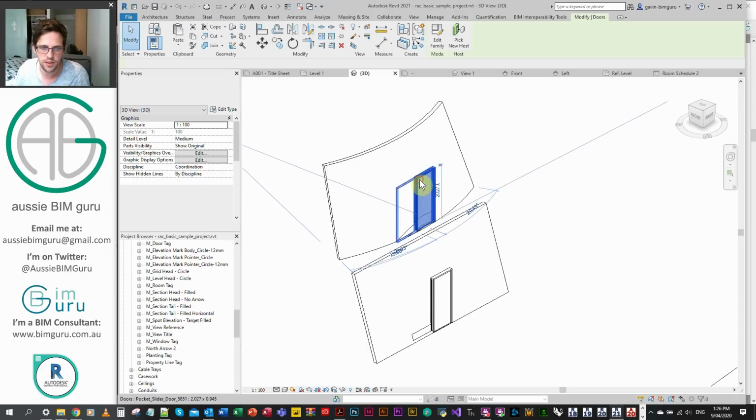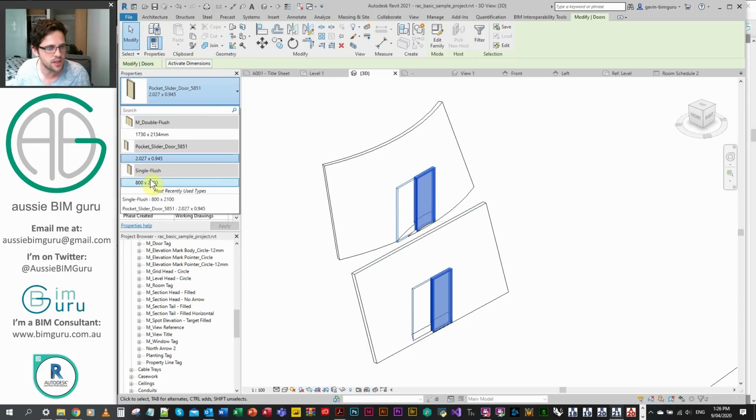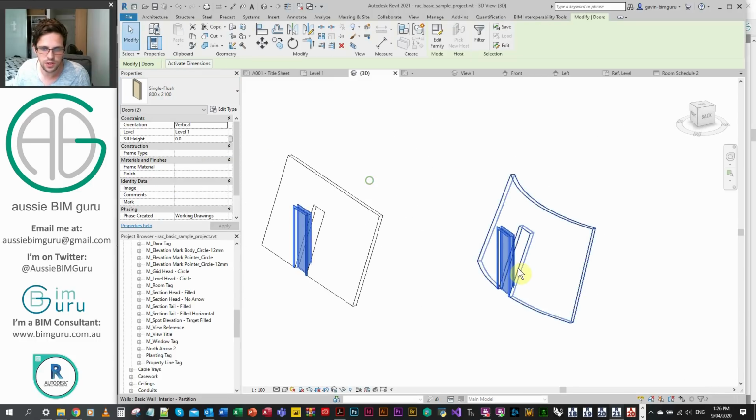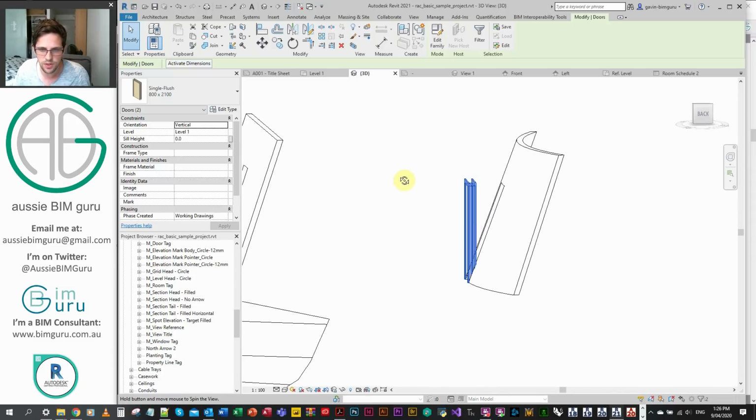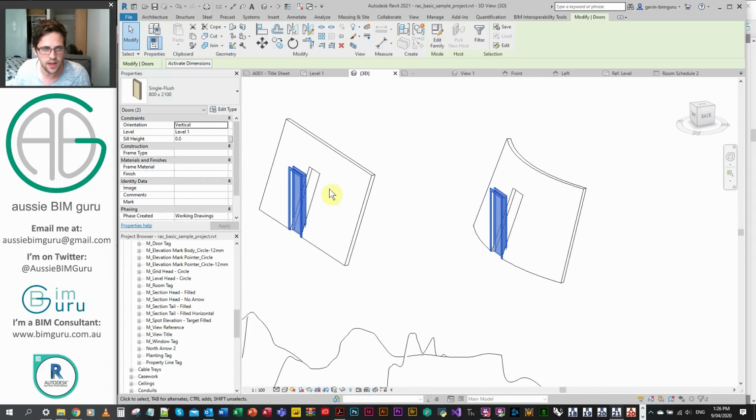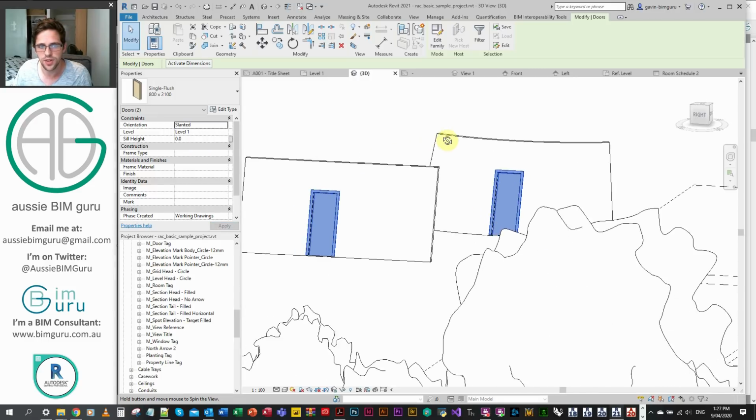And obviously that's pretty rubbish. They're all sitting vertically. I'll just pick some single doors. You notice the opening cuts right, but the door doesn't. The opening just cuts parallel. That would obviously have been pretty dreadful if that's how they worked, and would have made the tool pretty useless. Luckily, doors now have an orientation command where you can slant and bring it back.